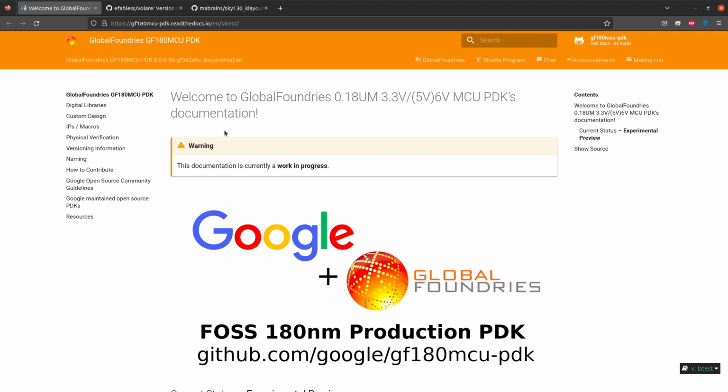Okay, so about the PDK, it has three combined options, A, B, and C. Each one of them will have certain options like number of metal stacks, metal top thickness, and MIM capacitor type. Here we will use the option C because it has all metal layers. We can design a full circuit from schematics to layout as the PDK contains all required files like schematic symbols, model cards, P-cell generators, verification files, standard cells, PNR information, technology definition files, and so on.